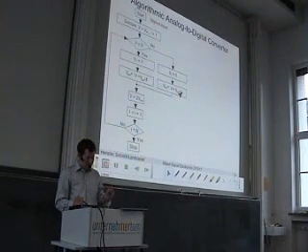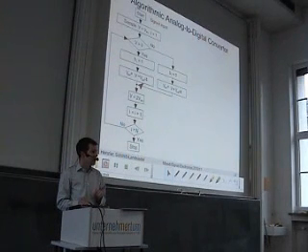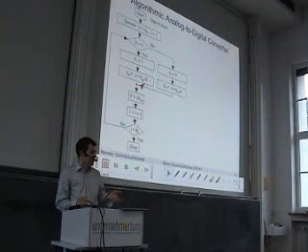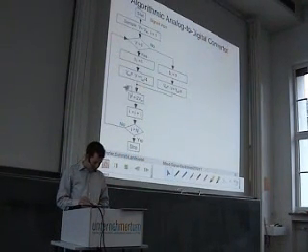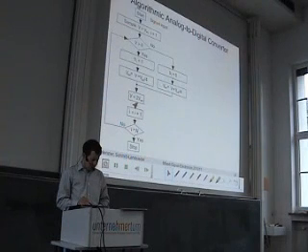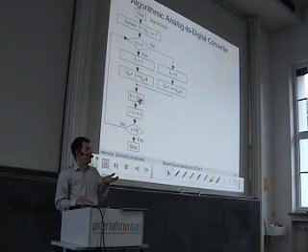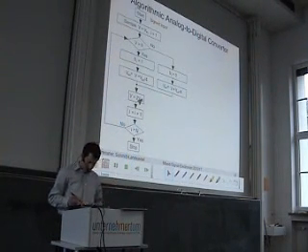And the new thing that you see here, it is always plus or minus Vref/4. It is not Vref/2 to the power of I, where I is the loop counter. But it's always the same, which is also easy for implementation. And then you get the remainder, you get an error. And this error is now scaled up by a factor of 2. How does this look like?